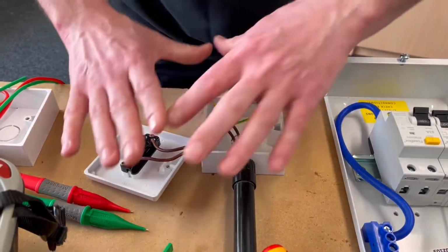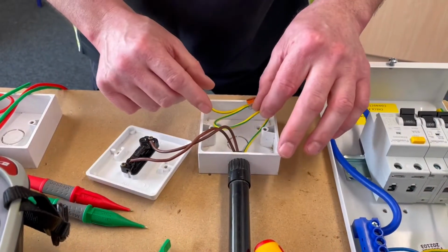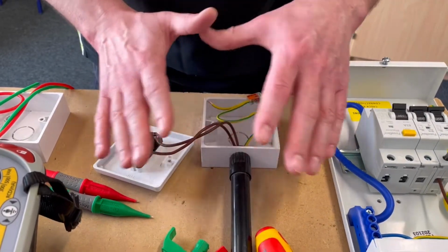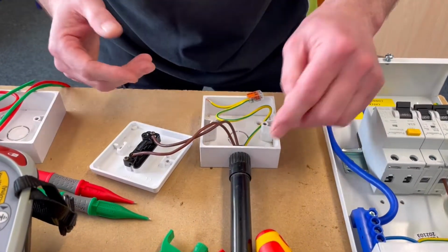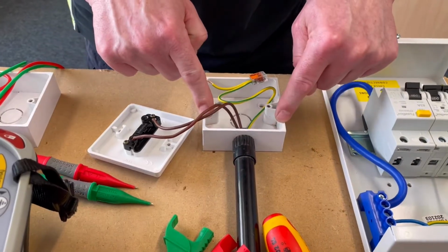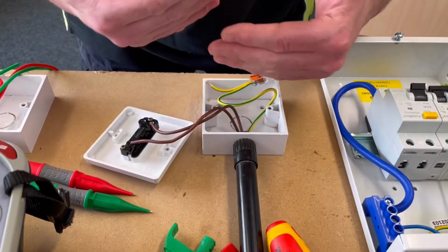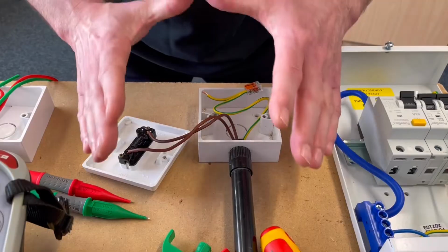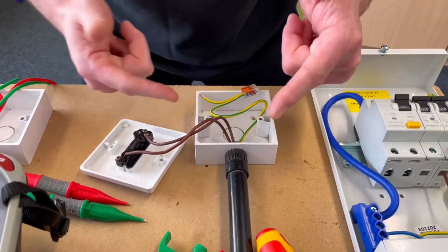When we're down at the light switch itself, all we need to prove is the CPC gets to here. It's a fully insulated system, so the CPC is here in case we change it for a metallic electrical part, which is an exposed conductive part. So it could be that we had a steel conduit, steel box and metal front, and therefore they would need to be connected to the CPC and prove that they are. And we've done that in previous videos as well.